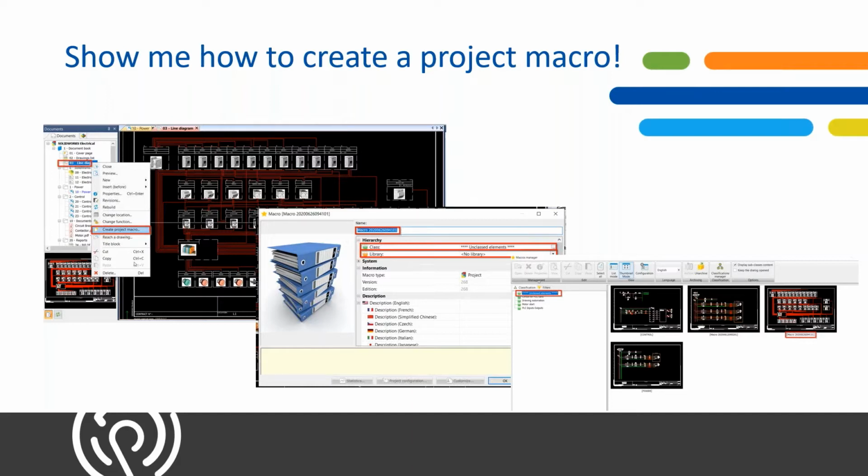And now we can click on that and we could drop it into our new project. Macros are super helpful. They allow you to place individual components, associate some components, or associate a whole sheet. Once you paste that into your new project, the macro manager, when it's all finished, allows you to attach other configurations or electrical circuits to that particular project, or you don't have to do that at all. But it's a very powerful tool.